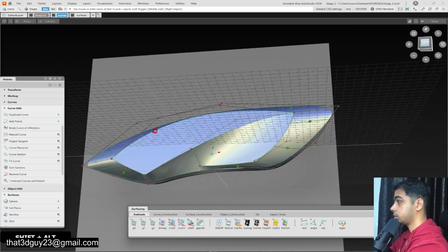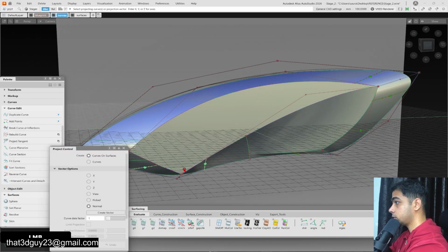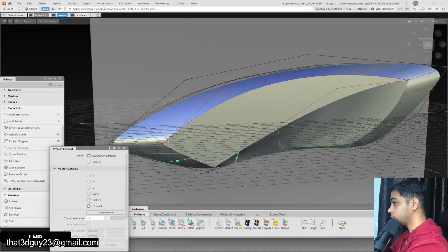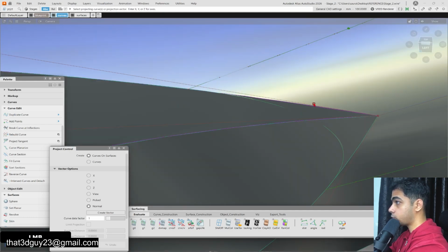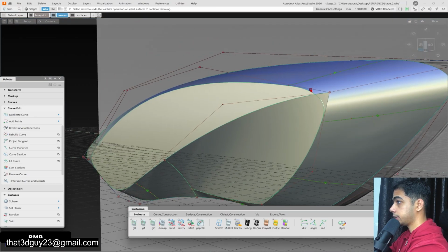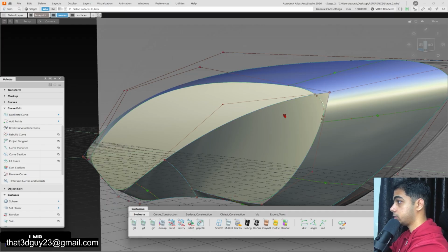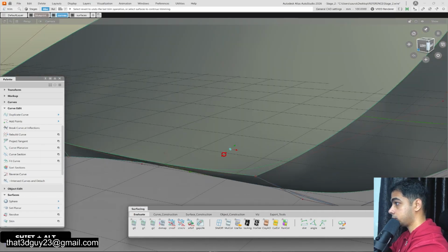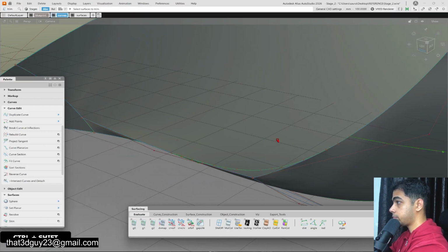Perfect. So we can also start trimming these. Having these trimmed out, we'll use normal because we want these edges to project themselves normally. So let's do that. Same over here. Let's trim, right? And project again, normal, trim. This one as well, project, normal, and trim.